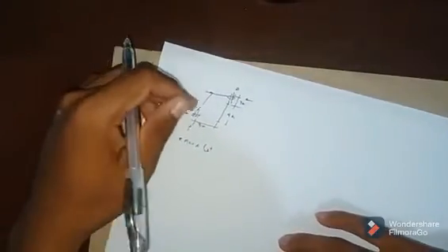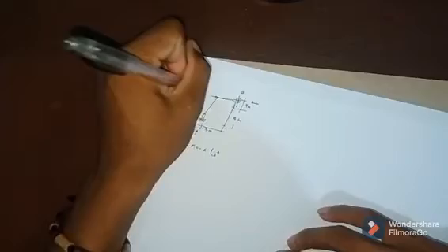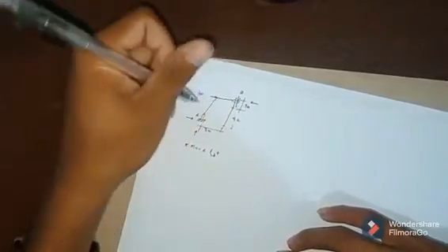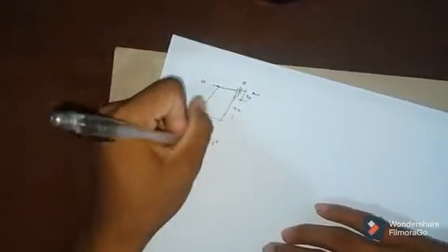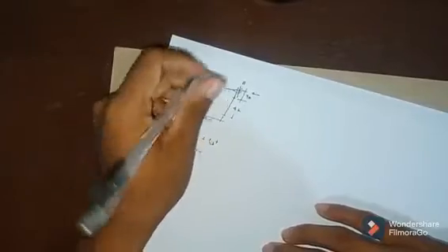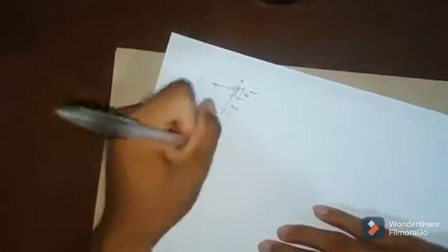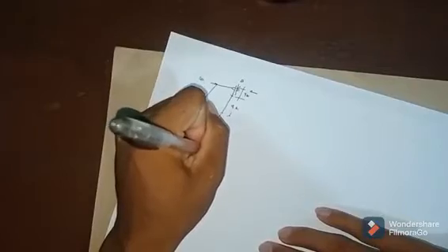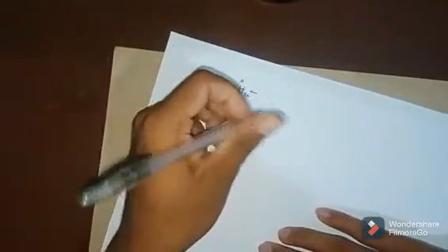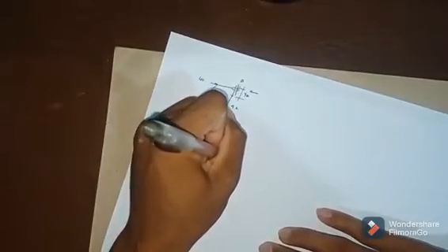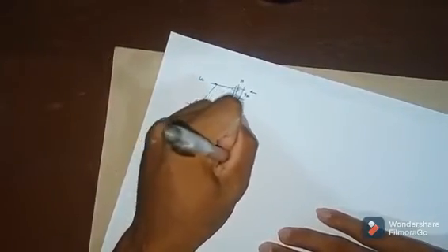So we have the 60 here, and it's rotating clockwise, so negative 60 times the arm length, which is 4, minus Bx, the vertical, rotating counterclockwise, so it is positive, plus Bx times the perpendicular distance, which is 8, equals 0.